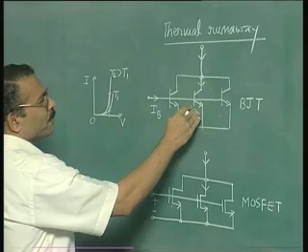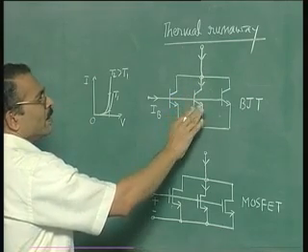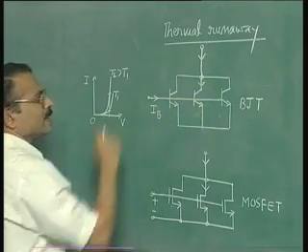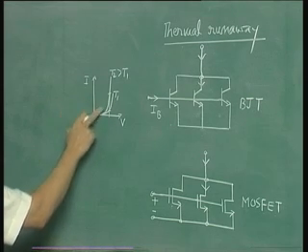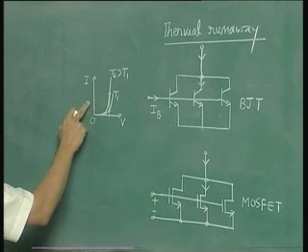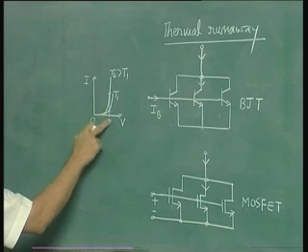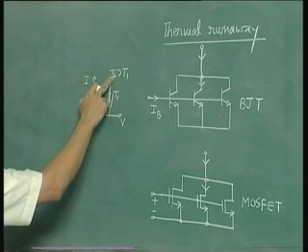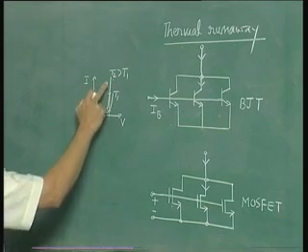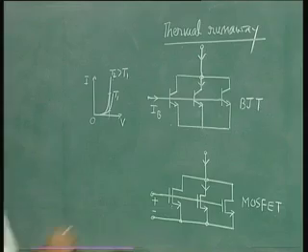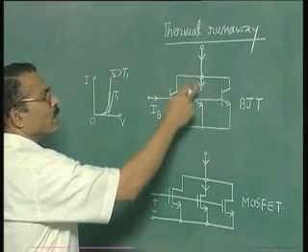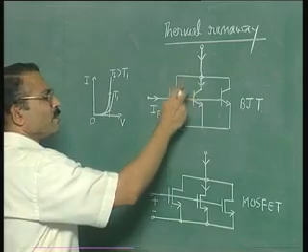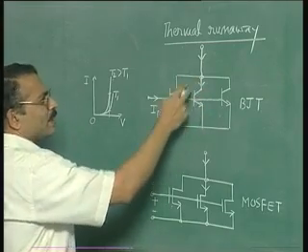It gets heated up, and as it gets heated up, it further increases the current, because you know, in a bipolar transistor the current voltage characteristics of the emitter junction is like a diode. Clearly see that for higher temperature, for any given voltage, the current is more. So here all the three have the same base emitter voltage. So here the current will be more if it is at a higher temperature. This will further increase the power dissipation and further raise the temperature.